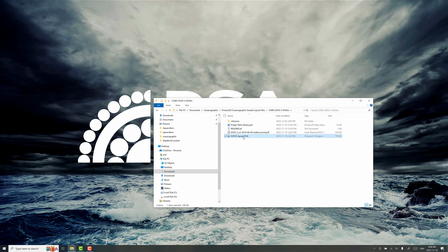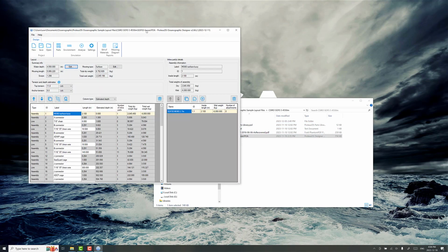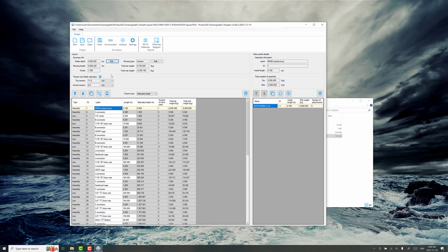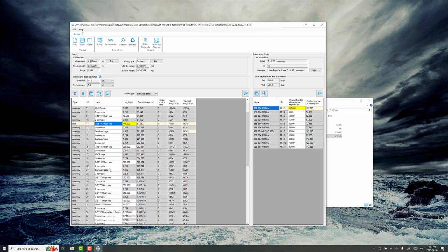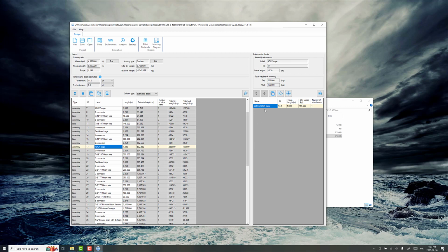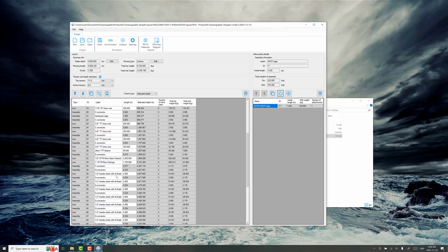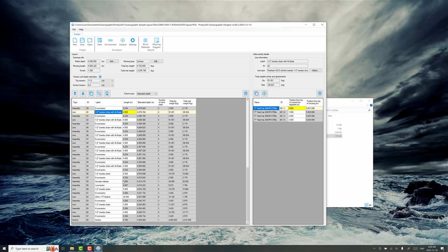And you can see if we double click on the sample file, here we have the mooring design for this system. It's a full ocean depth mooring, so in almost 5 kilometers of water depth and almost 6 kilometers of mooring line in there. There's a lot of different connectors and a lot of different sensors on the shots of wire rope through the entire system. Some interesting frames with ADCPs on them and other instruments. So it's an example of a system that has quite a lot of complexity. In fact, probably the most complexity I've seen in any oceanographic mooring.